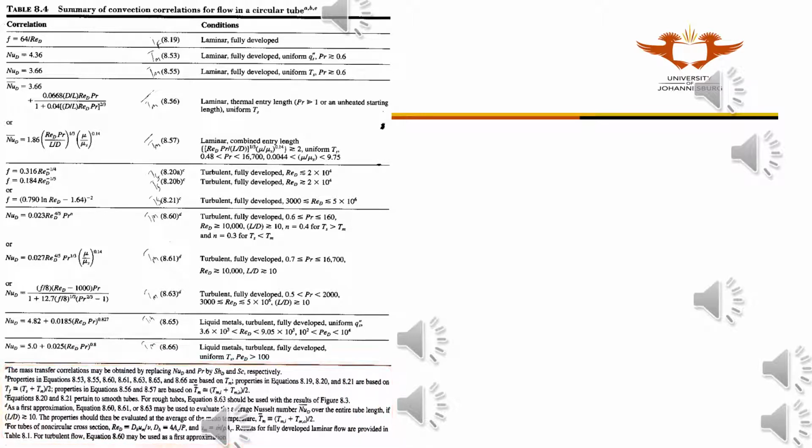For most Nusselt correlations, you need to use the mean temperature of the fluid for the variables in the Nusselt, Reynolds, and Prandtl numbers. If you are doing calculations for a long pipe, you need to use the average mean temperature for the pipe as shown.